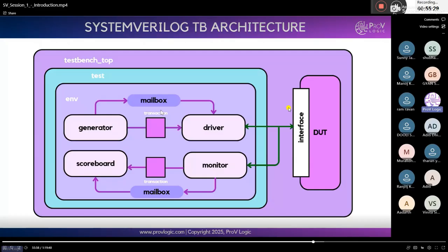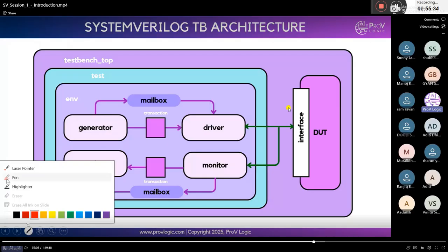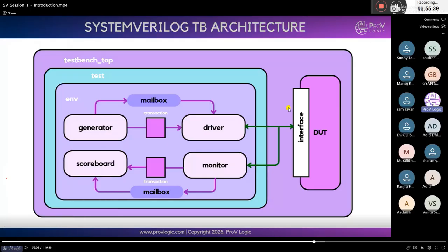fine. Okay, good. I will explain. So first of all, the design DUT, design under test, we need to interface with our test. In Verilog, whatever I showed now, the test is the same, but it is totally different here in how we interconnect our DUT to the test using an interface.